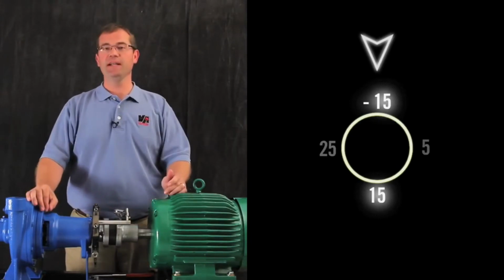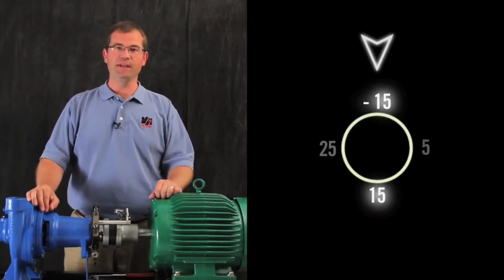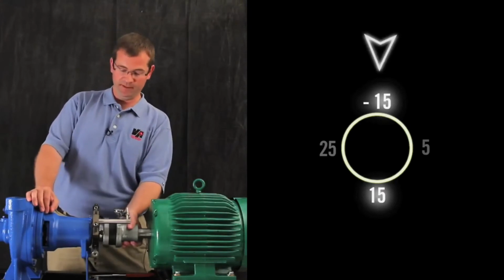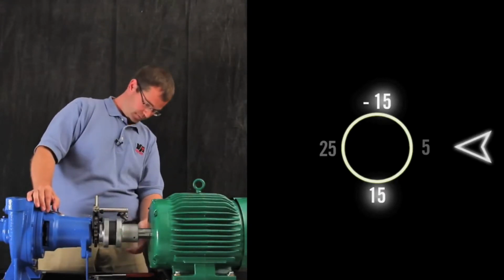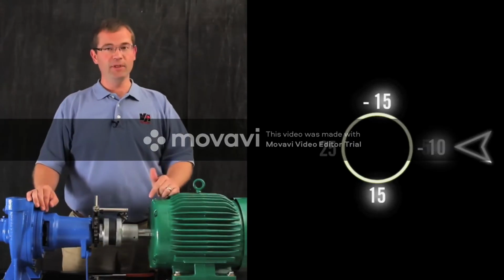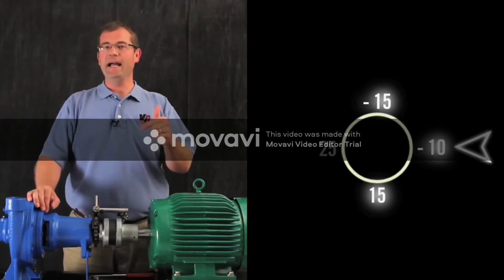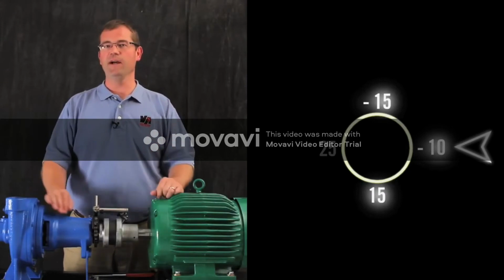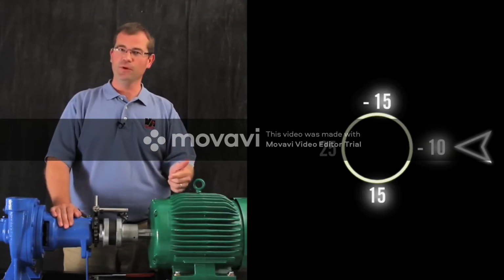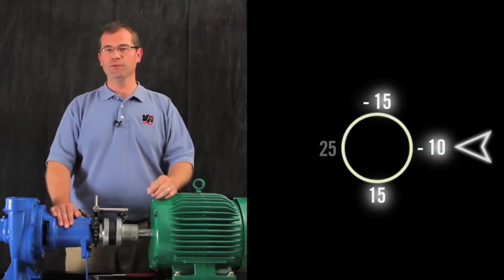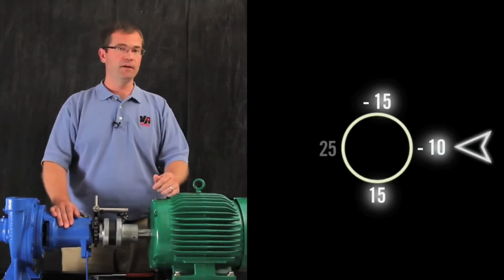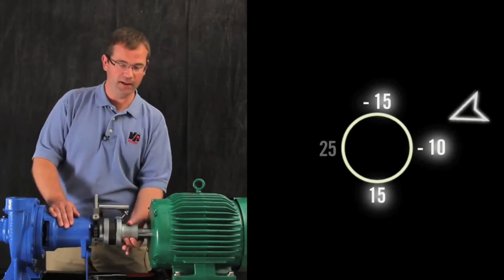So now if I rotate the dial to 3 o'clock, what do you think the indicator will read? Well, let's see. 10 mils, which is half of the TIR value that we got from before. Wherever we have the shafts rotated now, we're always reading true position. So what happens if I roll it to 9 o'clock?